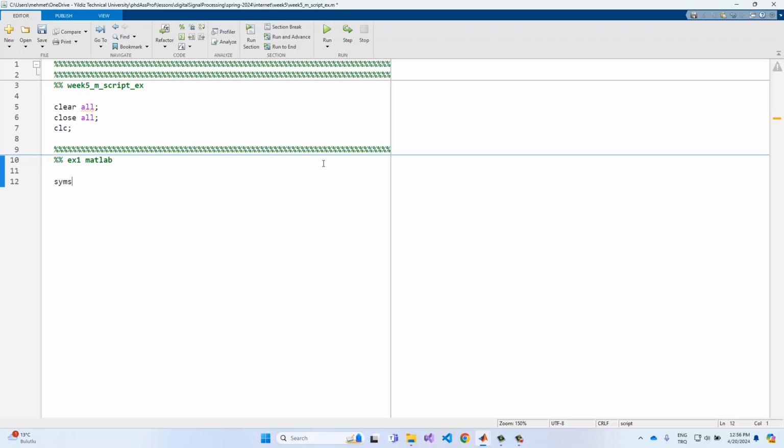Firstly we need to define the f(k) parameters in here, just like this one. This is a symbolic toolbox variable which is given in here with the parameter k. We can do that because Matlab enables us to define any symbolic function based on the variable. Also we need to give a, T the sampling period, and w, which is the angular frequency of our system.